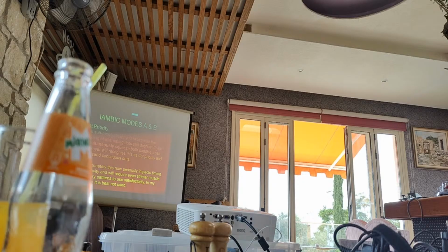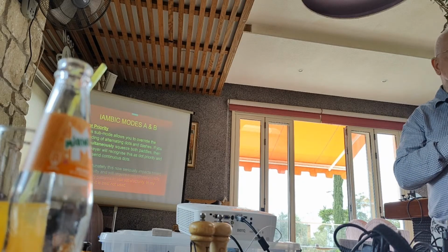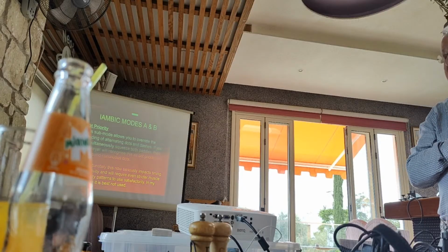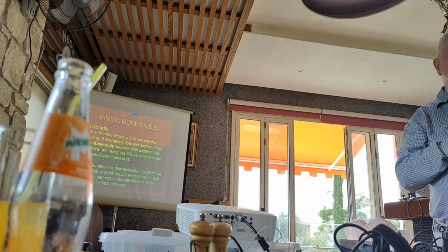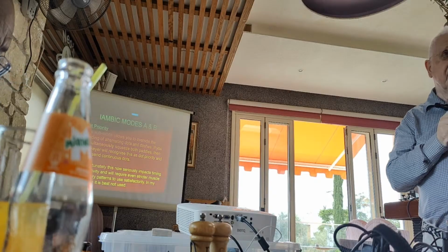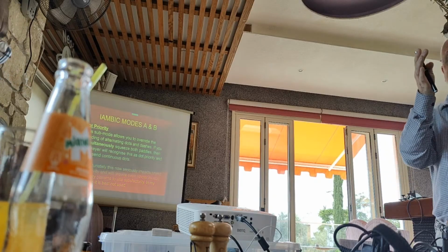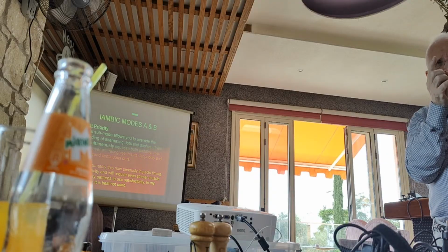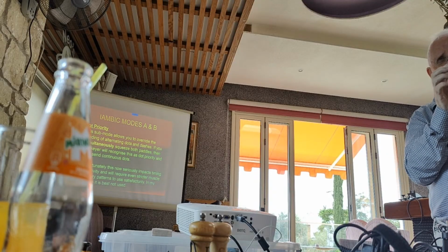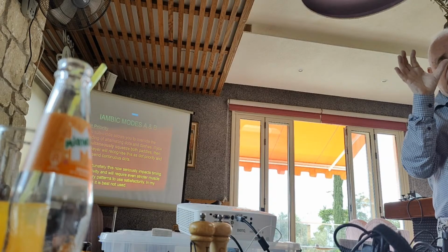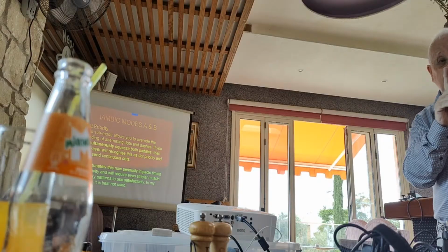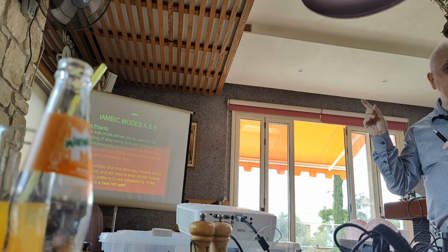Remember, you've got to suppress contact bounce. So if we start off at 20 words a minute, that's 60 milliseconds for a dot. You need about 10 milliseconds to make sure you're suppressing contact bounce. So there's another 50 milliseconds left to make a choice. If you're using dot priority, where in that 50 milliseconds do you decide this is dot priority or iambic? There's a timing gate in there. And this gets worse as you go faster.